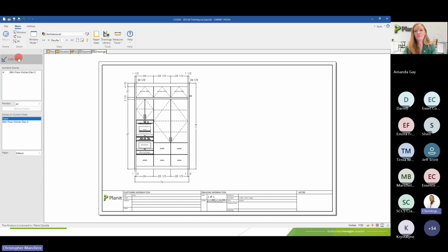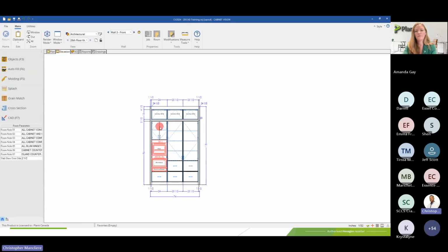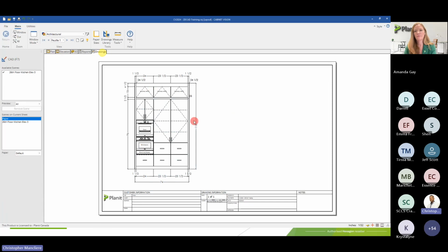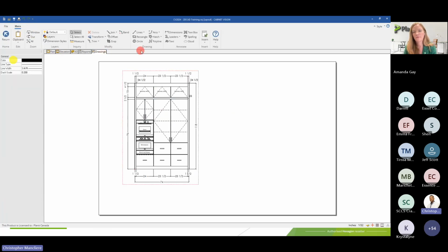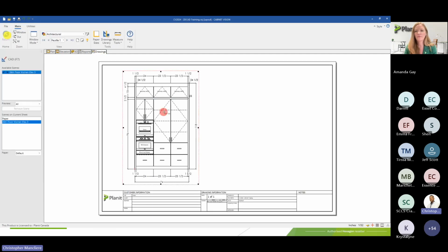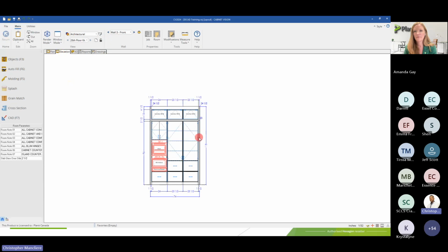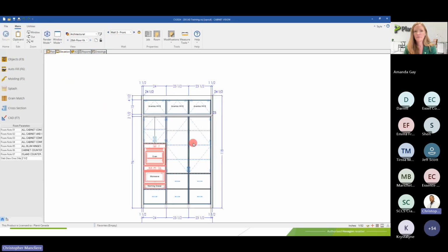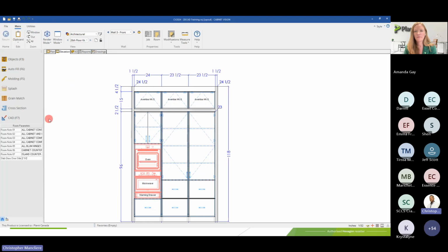So you can add CAD. When you add CAD from the drawing, that will not write the CAD on your room. That will only stay in the drawing tab here. So for example, if I select my elevation view, click CAD and add a text right here, type 1, 2, 3, click OK. This text is only being saved for this scene in my drawing, whereas if I go back to my actual job elevation view, it doesn't have the text.